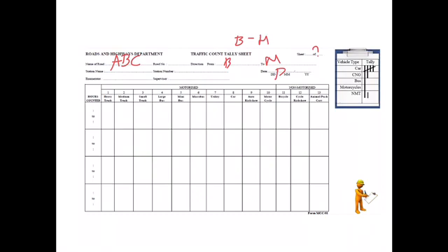Okay, and next, we can see here, first we have to note down the hour counted. Okay, what is the time interval you are conducting the survey. For example, if you are conducting the survey from 9 to 9:15, that time has to be written here, and then here 9:15 to 9:30. So like that, note down the timing, write down every 15-minute interval.